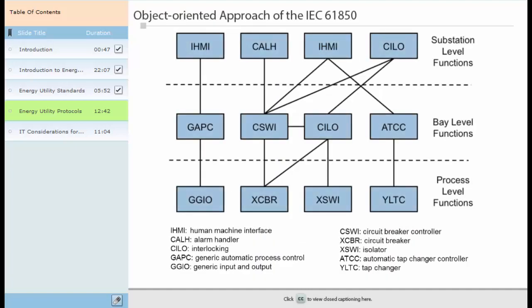Standard IEC 61850 uses an object-oriented approach, a key benefit of the open standard over legacy protocols. According to this approach, control, protection, monitoring and metering capabilities, as well as physical components, are divided into small virtual units called logical nodes. Multiple logical nodes communicate with each other to provide specific functions such as voltage control or generic automatic functions.